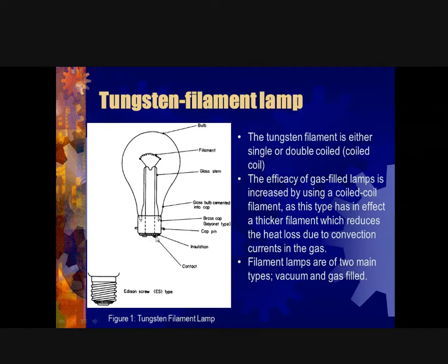If this is a particular single contact lamp, in some cases one pin will be your live pin, and one will be your neutral pin. In some cases, like a car bulb, if you're using a push-in car bulb with a single contact, the side will be your negative, and the contact at the bottom will be your positive. So when you actually fit it inside the indicator, your headlamp or your brake lamp, then it will work in that manner.